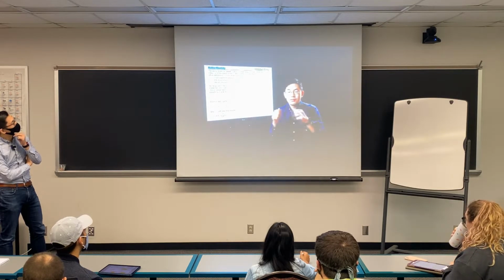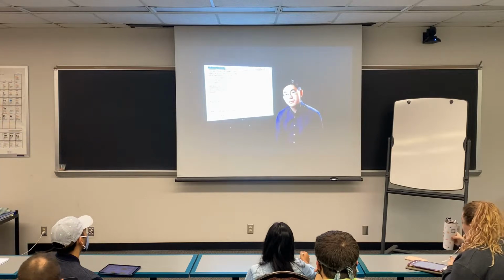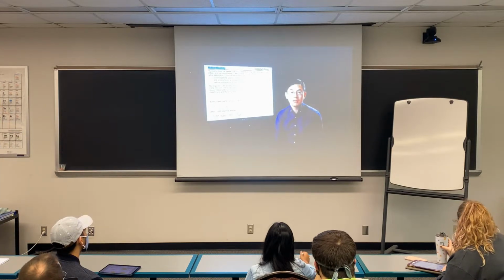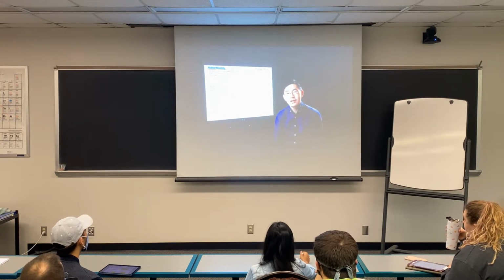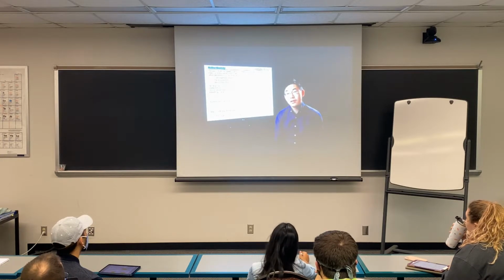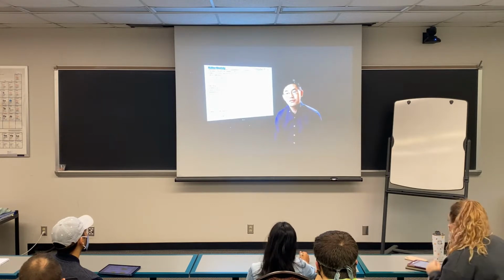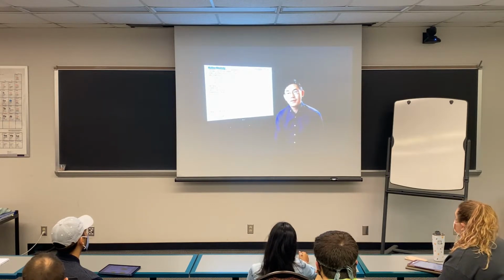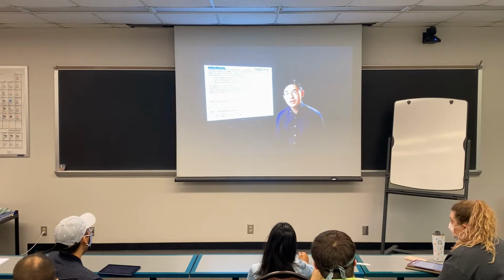If you imagine stretching a chain, at the initial stage it will be a Gaussian coil. But if you stretch the rubber a lot, say 4 or 5 times its initial length, then your coil is no longer a Gaussian coil; it's a very much elongated coil, and your value will be different and depend on the degree of strain. So the first assumption does not hold very well at a high degree of strain for rubber material, and we will see why that's the case and discuss what the results look like in today's lecture.